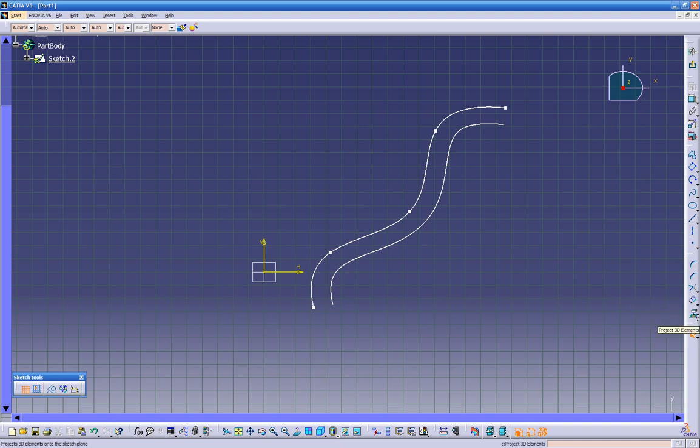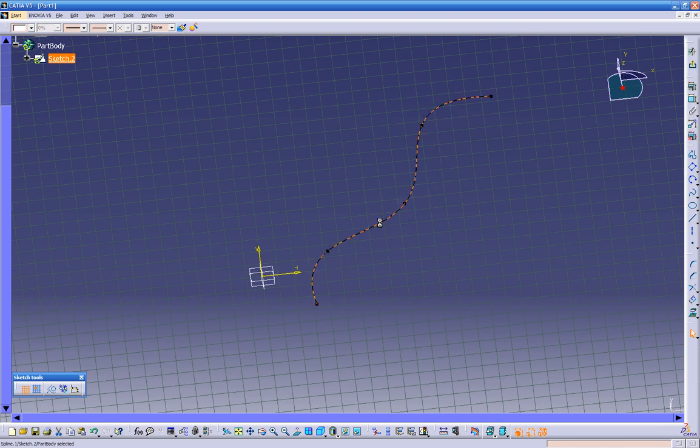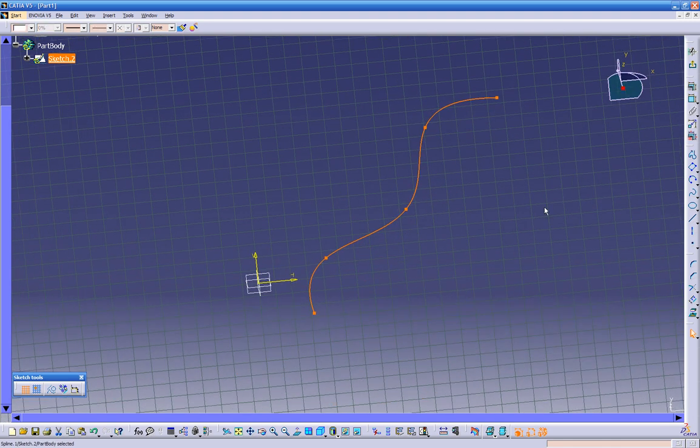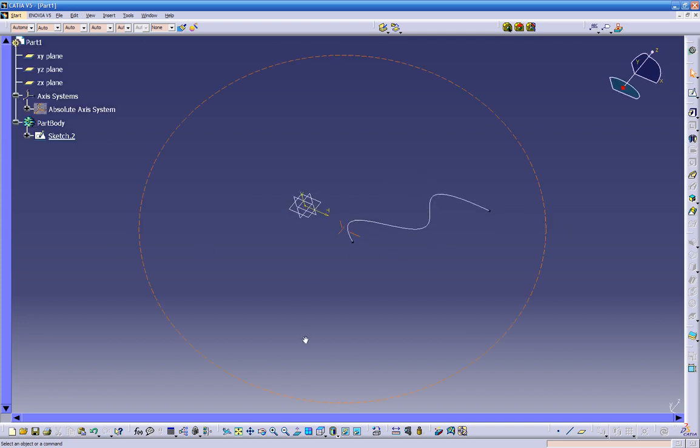So pretty much this option right here is pretty good. We use it to project curves from a model into this sketch. So I'm gonna make a quick surface. Just for the heck of it, I'm gonna create this right now. You don't have to learn this pretty quick, but I want to create a quick thick surface over here. So you can click on the pad.